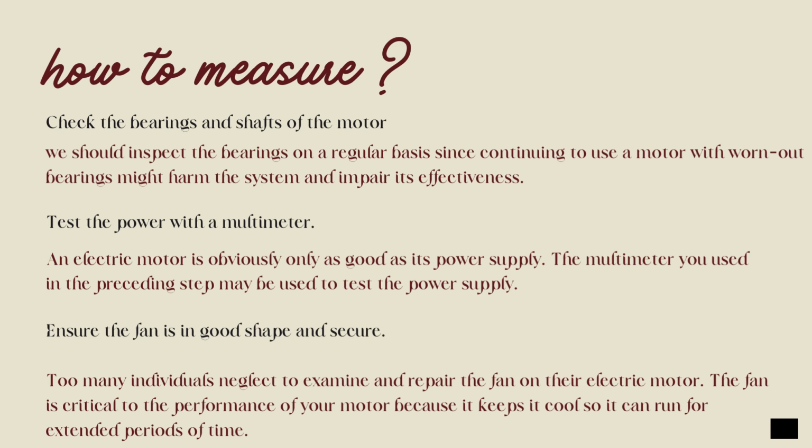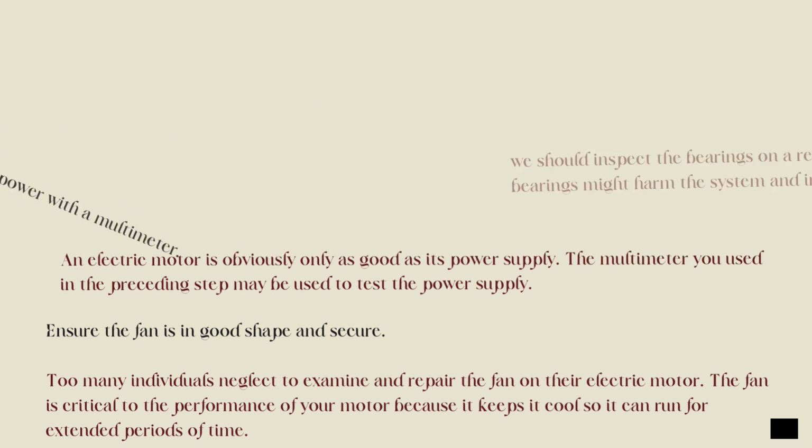The final step is to ensure the fan is in good shape and secure. Too many individuals neglect to examine and repair the fan on their electric motor. The fan is critical to the performance of your motor because it keeps the motor cool so it can run for extended periods of time.